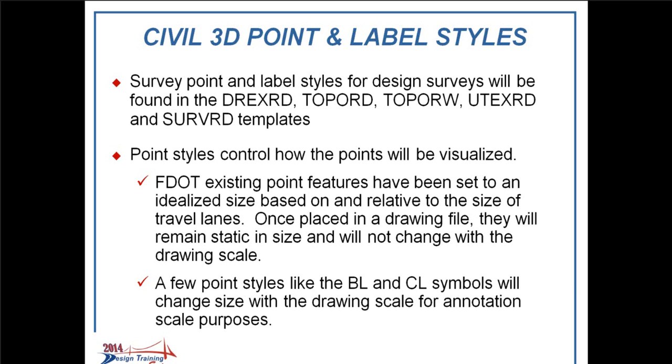It's just an idealized size that's in relation to, say, 12 feet of pavement, where we do not want a manhole cover scaling up and beyond the size of the pavement itself. We always want to keep all these points relative to what a roadway would look like. So a few point styles like the baseline symbol and the centerline symbol will change size with the drawing scale for annotation scale purposes, but those are the only